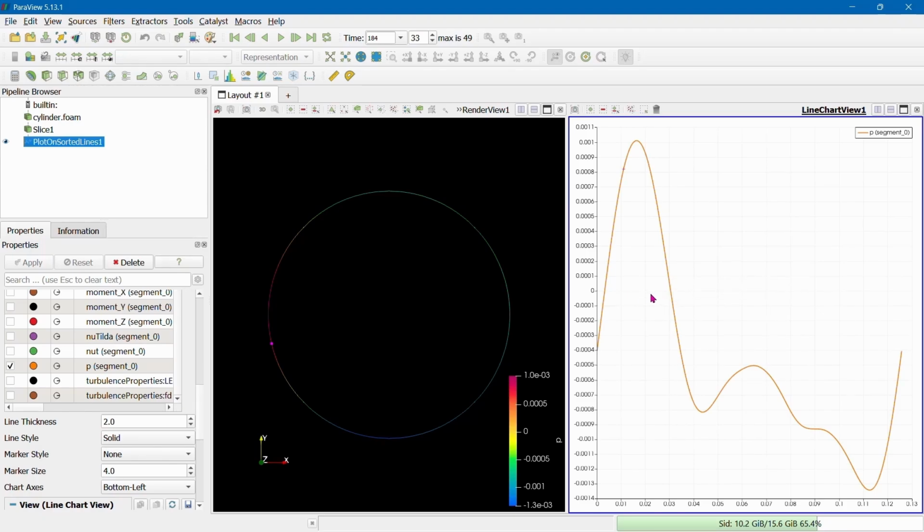So right where you have pressure 0, there will be a stagnation point. Essentially you will have flow that no longer stays there and it is going into this negative values right there. So this is a great way for you to again understand what exactly it is that the pressure data is trying to tell us over this entire cylinder.